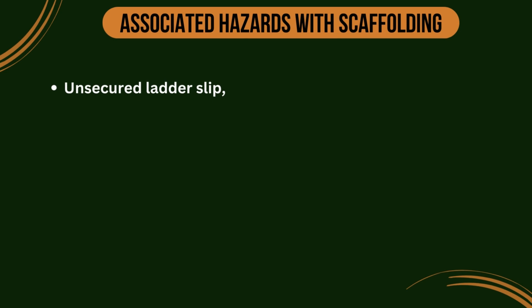Means we are using ladders also in the scaffolds for going from one level to another level, and if we have not secured these ladders properly, then these ladders may slip, and because of this ladder slip there may be a case of fall of a person which may result in a deadly accident. So we should ensure to secure the ladders properly in the scaffold.